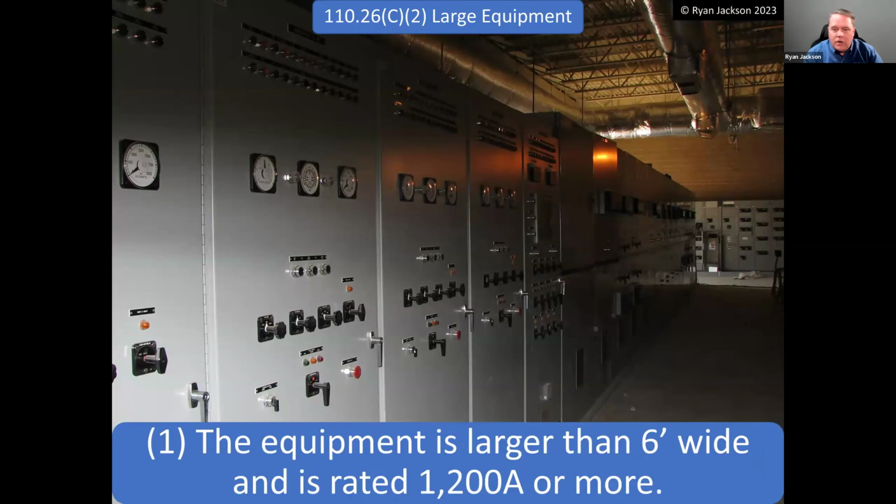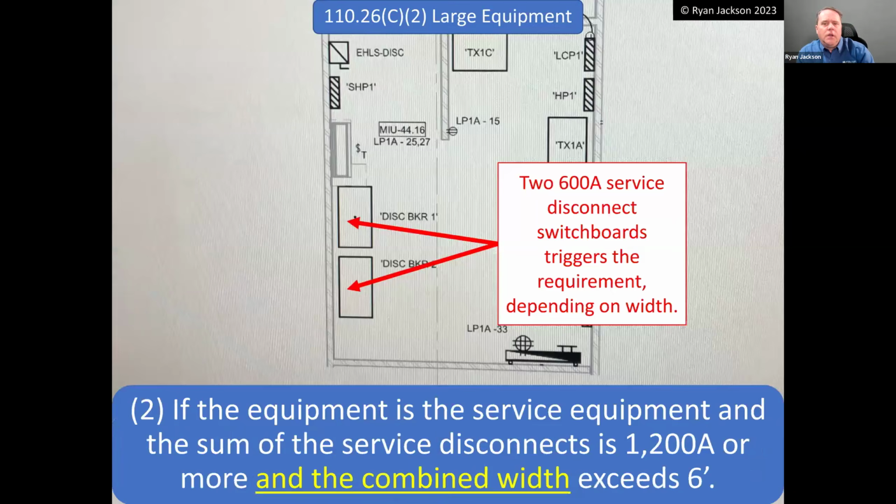So on this picture here, you need to be able to leave it on that side and leave on that side. Or, due to the 2020 code, if the equipment is the service equipment, which is the first place you can shut off the utility, and the sum of the service disconnects is 1200 amps or more, and the combined width exceeds 6 feet. All right, so looking at this picture here, each of those that I'm pointing at are 600 amps, total of 1200 amps. I need to have an exit on each end of the working space.